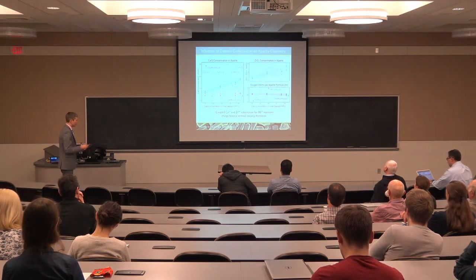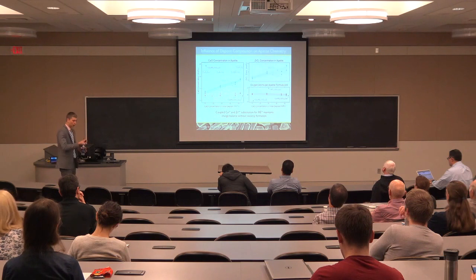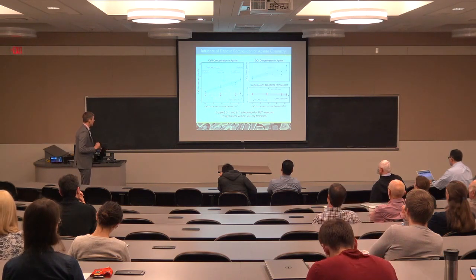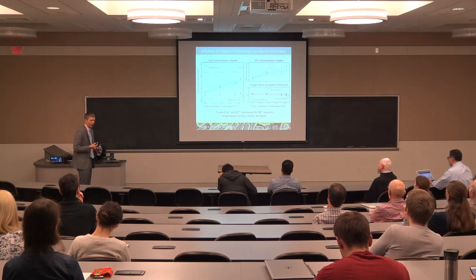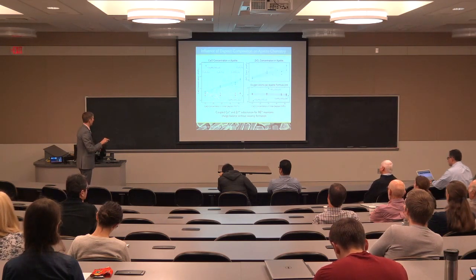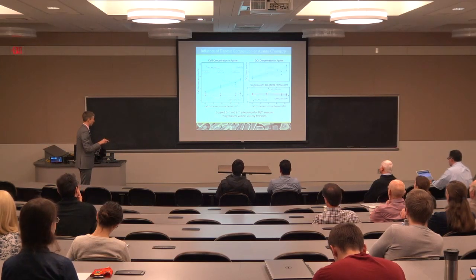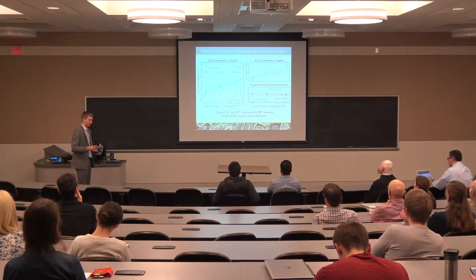And if we look a little bit further, what we find is that this difference between the zirconia-containing cases and those without zirconia is the fact that a little bit of zirconia can go into the apatite structure in the end, and that zirconia charge balances calcium substitution. And so even though we have a range of calcium substitutions, if we add up how many oxygens we have per apatite formula unit, it's about constant.